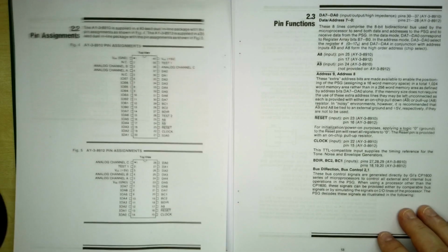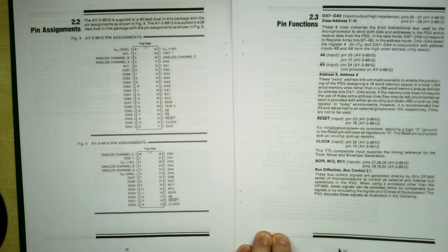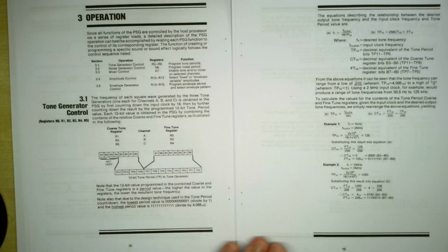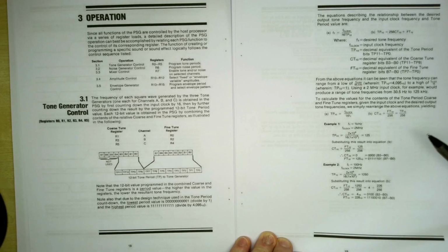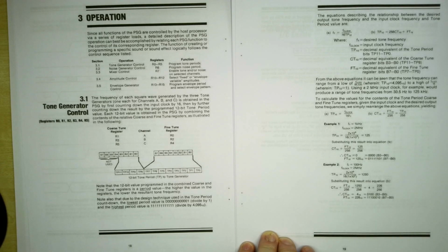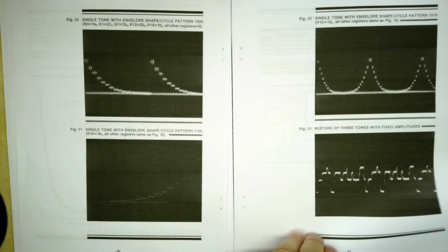So this document includes a lot more information on all the pins and everything. I've gone through reading all of this, and I'll be feeding the output of that into the design. So the clock decision is quite important because the frequencies that we get out, depending on the configuration values, will depend on the frequency. I think the examples here have used a 2 megahertz clock. We could use a 2 megahertz clock, or we might just use a 1 megahertz clock. So this has then got the detailed information on each of the controls that we'll be looking at when we're doing the programming for this. Similar information that we saw in the datasheet, just a lot more detail.